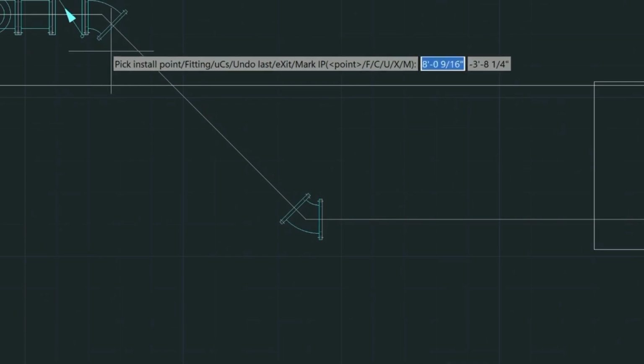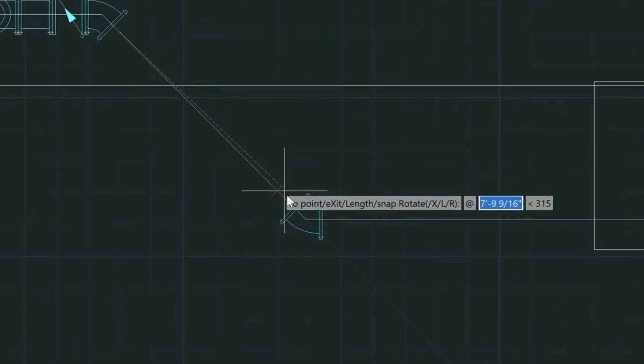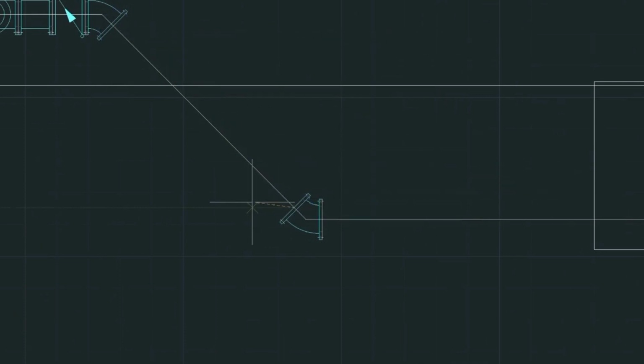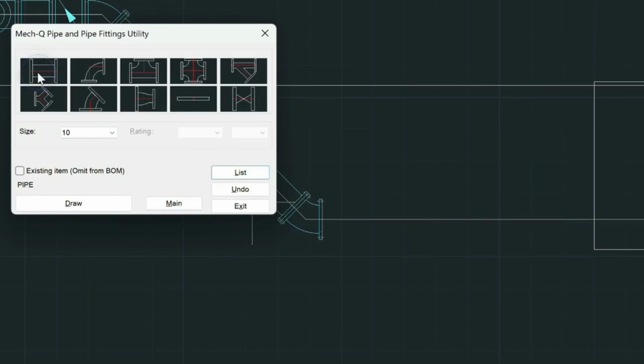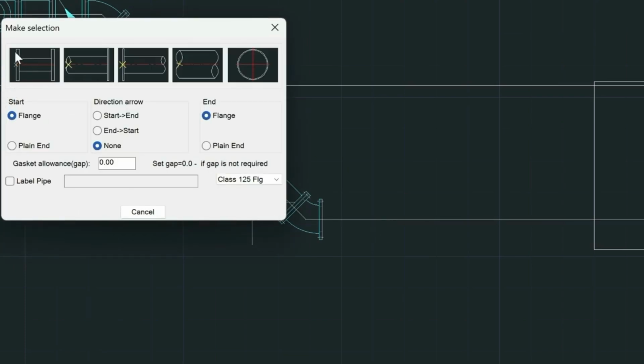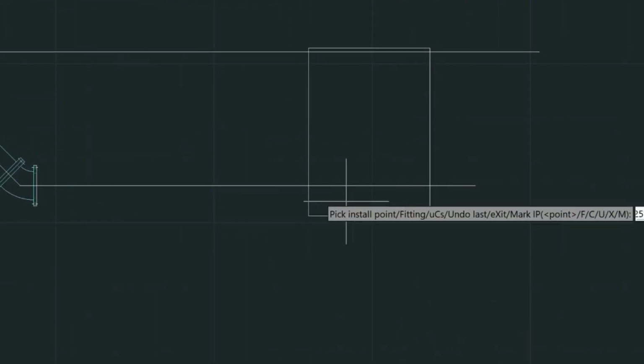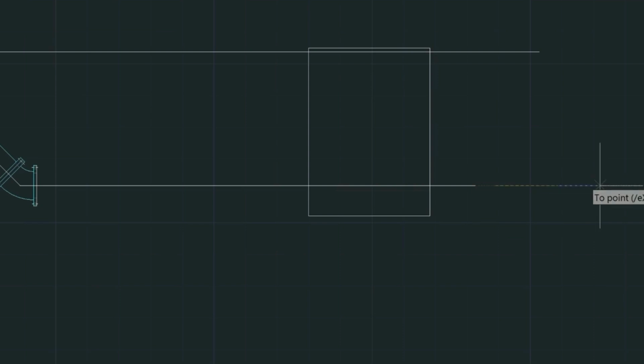Again, let's do the straight piece here between the two 45s. We'll come up here this way, left click, and enter. Just do a couple more. Choose left click and draw, and we'll put one at the end here. We'll come out 8 inches and we'll choose enter.